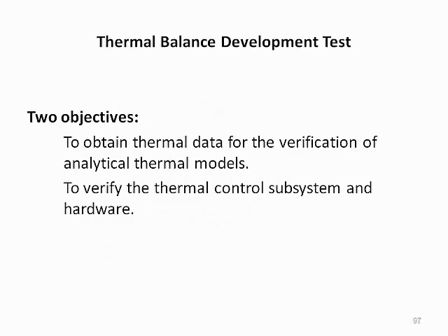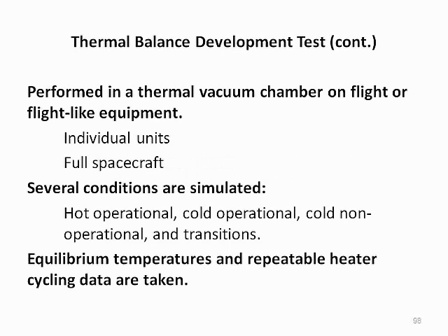Thermal balance development tests have two principal objectives: to obtain thermal data for the verification of analytical thermal models, and to verify thermal control subsystem hardware. Thermal balance tests are performed in a thermal vacuum chamber on flight or flight-like equipment. They can be performed on everything from individual units to full spacecraft.